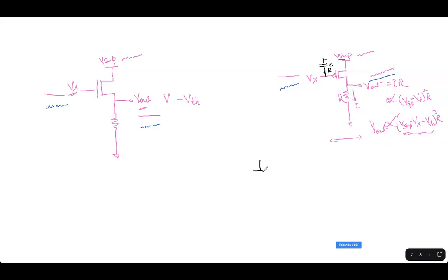Whenever there is an RC like this between two nodes, of course, the low frequency will not be coupled. That's sure. High frequency will get coupled. From what frequency? There should be a frequency threshold from which there is good coupling.